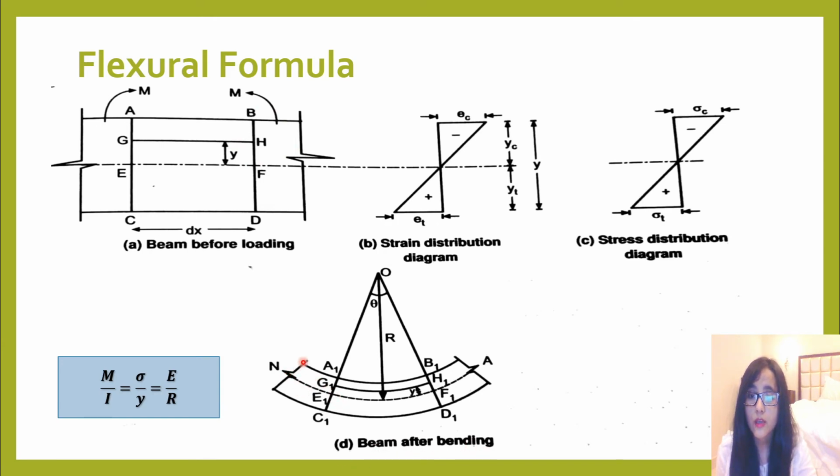तो यहाँ पर जो भी moment produce होते हैं, यहाँ पर sagging nature का moment produce होते हैं. और यहाँ पर जो neutral axis line है, neutral axis line के ऊपर you will have a compression zone and below this neutral axis line here you will have a tension zone. This is for a simply supported beam, right? Now यहाँ से आपको पता है, जब moment से bend होते हैं तो simply supported के लिए it will form this kind of bending moment.